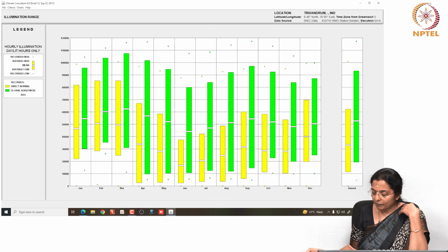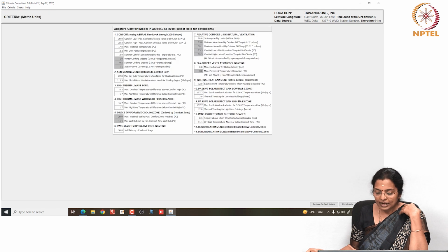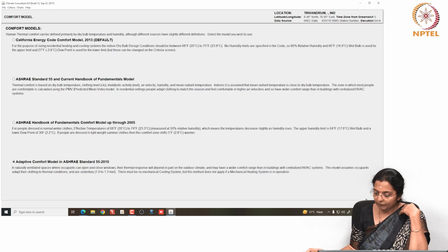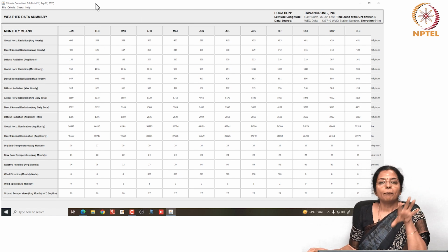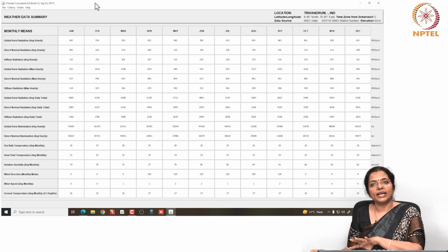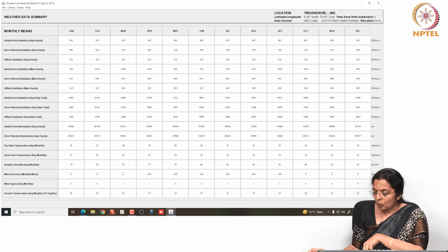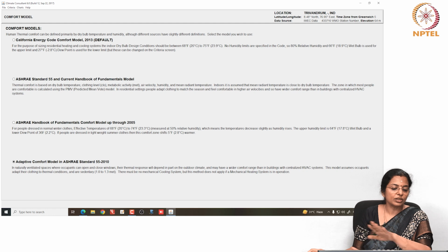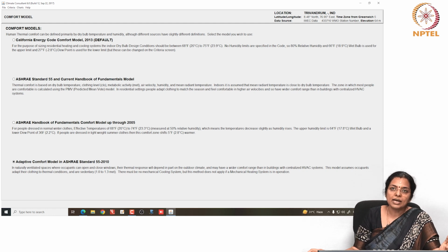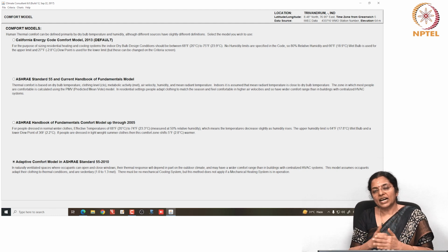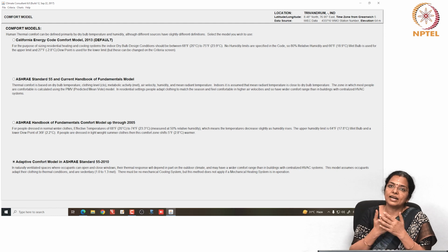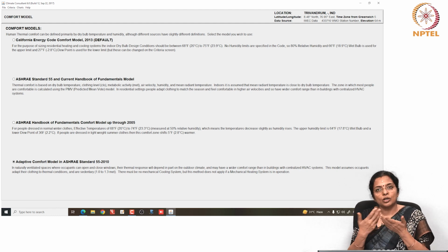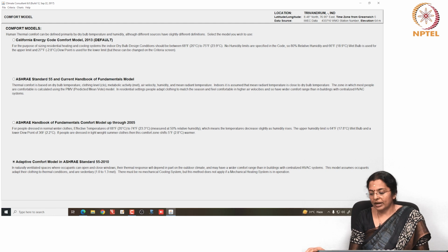Those are all just like Mahoney's table. The data you enter is just like Mahoney's table. But how this data is interpreted, how the programming happens, will depend primarily on the comfort model you choose and the comfort band that each of these comfort models assign for a particular category of factor that influences thermal comfort, which is clothing level or metabolism and so on.